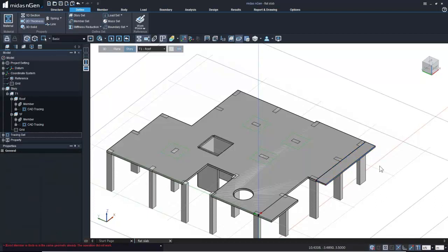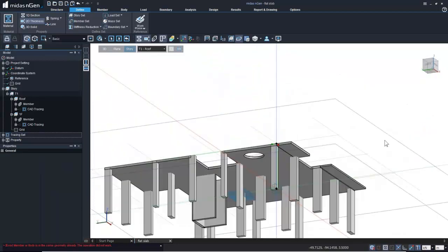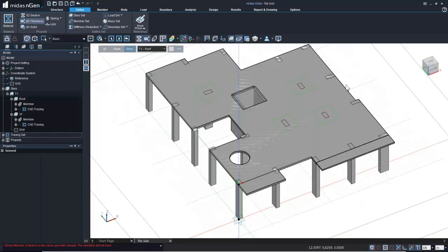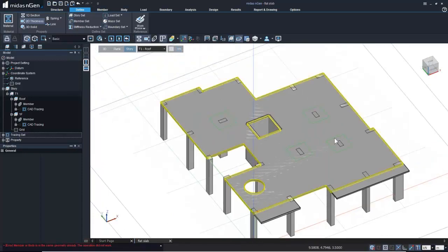and that's how I can modify the thickness of the slab. Alright, now it's important if in case you have the difference of thickness in between this particular flat slab area, then you need to divide this flat slab and make an area over there separately for a flat slab.